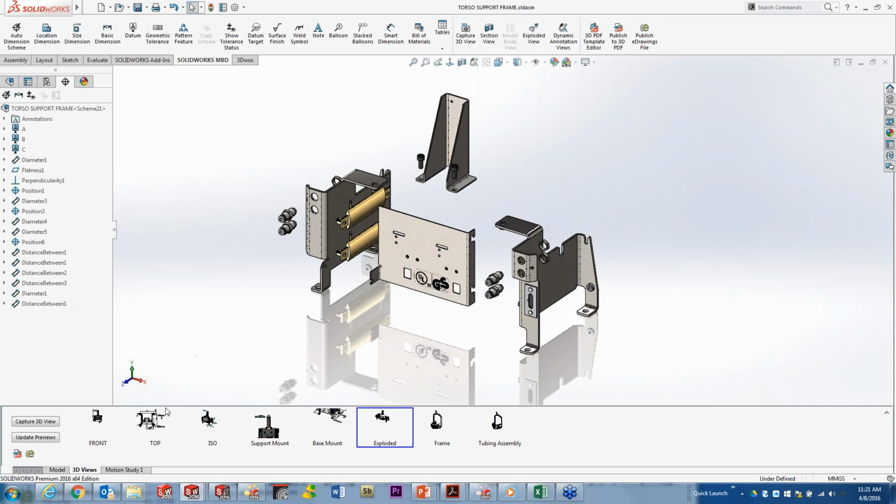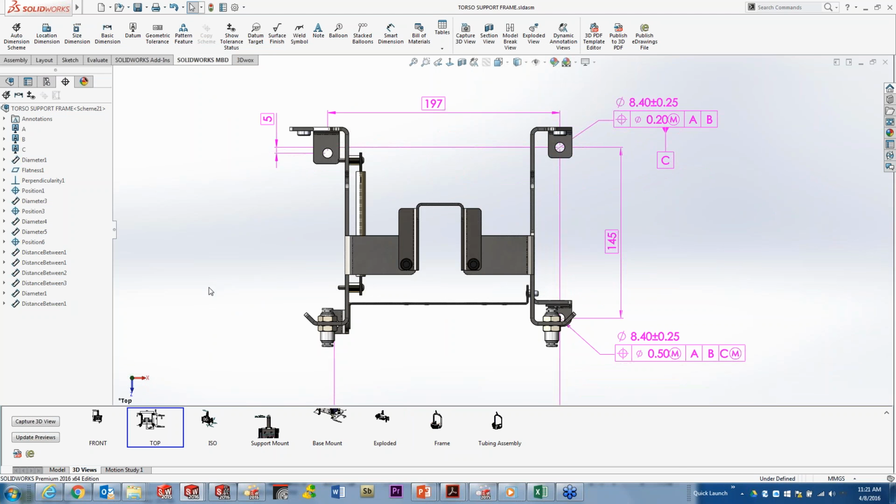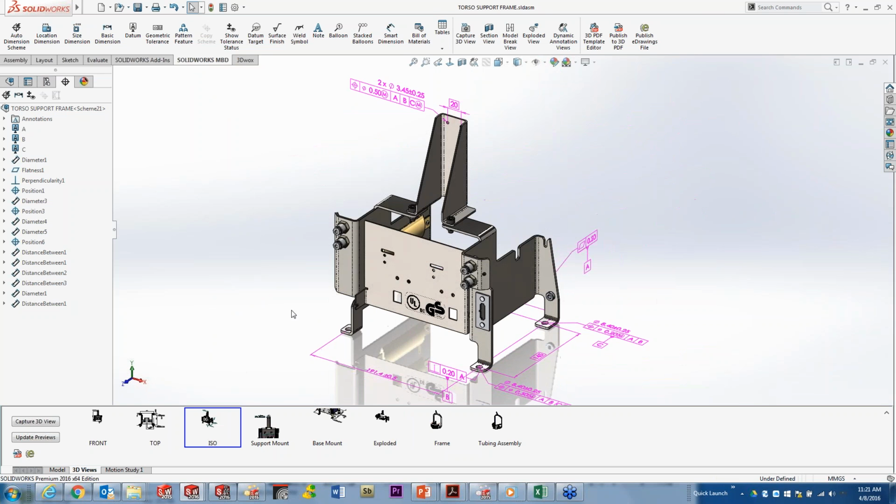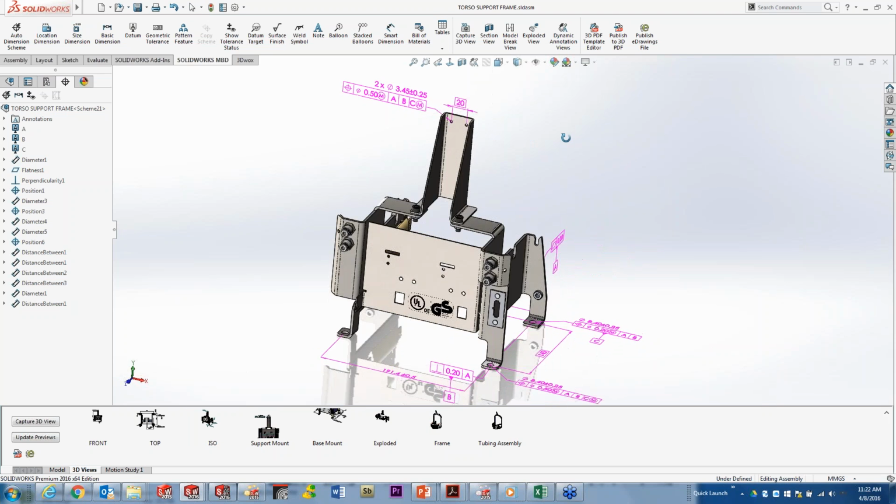Now each of these views is something that we're setting up essentially to be utilized in the downstream communications tool. But as we're creating things here in 3D, we have the ability to depict these. Now we also get a great little bit of talkback. When you hover over an annotation like this GD&T control frame with the position tolerance, you'll see in the lower right-hand area that it actually shows you the XYZ origin that it's based on and gives you some positional orientation based on these types of inputs. So it's a pretty interesting way to be able to see this once again in 3D.